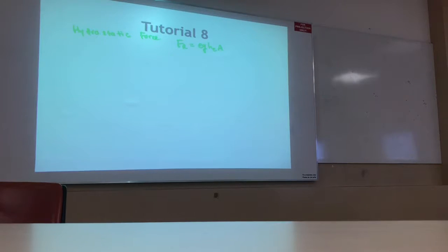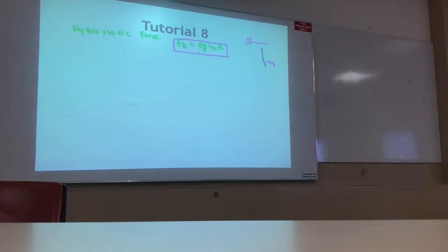Okay? This is the equation. You have to remember. Alright. Hc indicates the distance from the water surface to the centroid of the object. So this is the object, centroid is here. So distance from the water surface to the centroid is called HC. Or in some books people write YC, also the same thing.